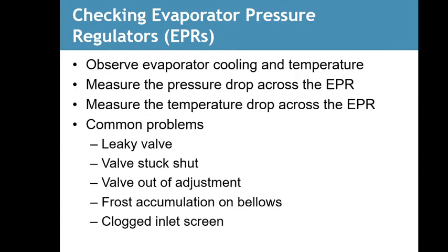Checking evaporator pressure regulators, EPRs. Observe evaporator cooling and temperature. Measure the pressure drop across the EPR. Measure the temperature drop across the EPR. Common problems: leaky valve, valve stuck shut, valve out of adjustment, frost accumulating on bellows, clogged inlet screen.